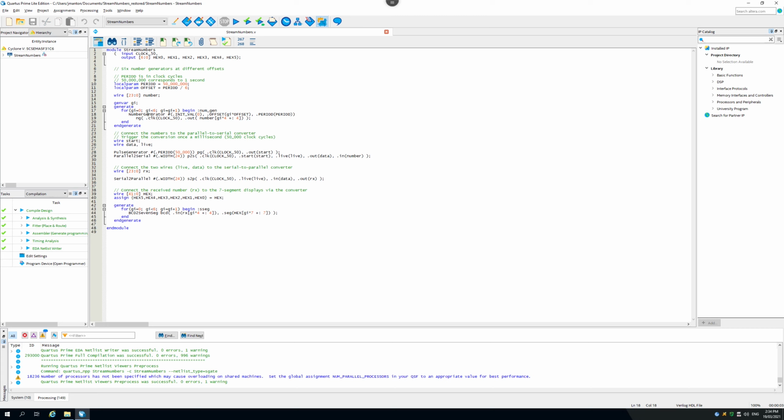When we look at the number generator module later, we'll see that it has defined 3 different parameters, and I can give them values. These are not values that are passed in on wires in the FPGA. This is beforehand at compile time, so they're going to be fixed for the design.